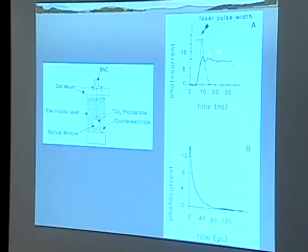I'll point out, when you're looking at the fast time scale here, even though we've done a lot to minimize noise, you have, boy, if we were doing NMR spectroscopy, we would call that ringing going on there. That is, we have a bit of an impedance mismatch between our oscilloscope that we're putting this out to and our wires and our cell here. And so we have some signal bouncing back and forth. And all this ringing here is due to that. So the real signal is on this longer time scale here. So that's the experiment.